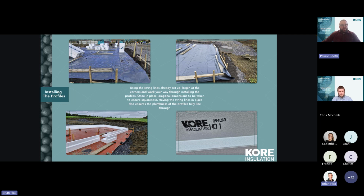So again, you typically start at your corners, and work across the drawings that are specifically done for each individual foundation. They'll have measurements on them so you can check your angles, and make sure everything is 90 degrees and square in place. You work your way across, and you'll see that typically every profile will have a specific number, a reference to the installation drawings. Each foundation has its own specific installation drawing, which makes it very easy to follow and install the system. It's done step by step to help you install the whole foundation system.